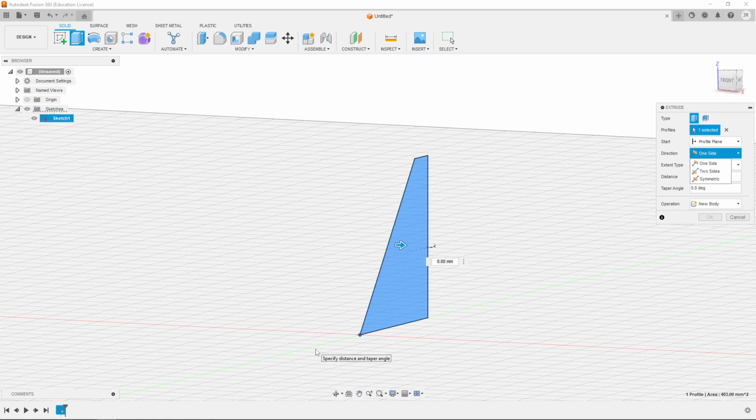If you have something that has symmetry across your entire object that you're designing, then that could be a really helpful thing to do. But of course, if that's the case, then we have to make sure that our math adds up. If this thing is 26 millimeters long or whatever number, we only have to extrude it halfway because the other half is done for us symmetrically, right? So we have to be aware of a lot of things as we're doing that. I'm going to stick with one side for now, and we'll go from there. Again, we're not going to talk about this one just yet, but we'll come back to this. It will definitely be useful.